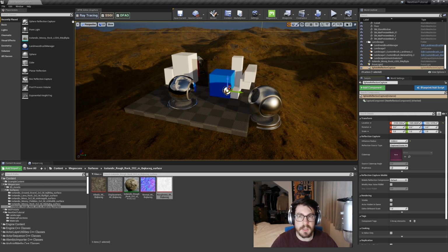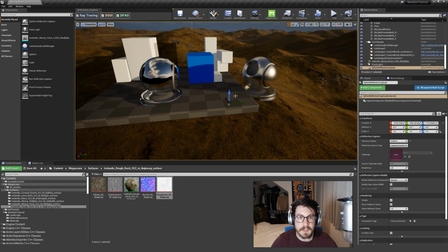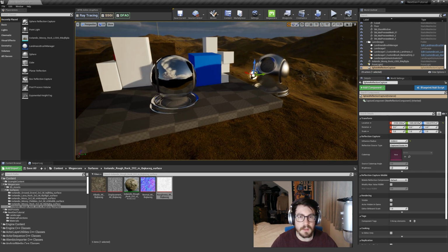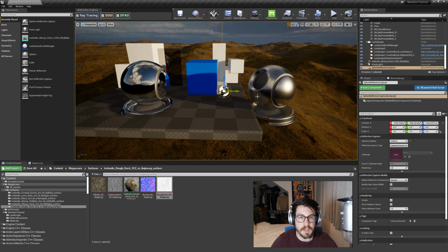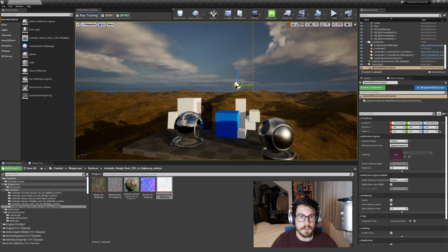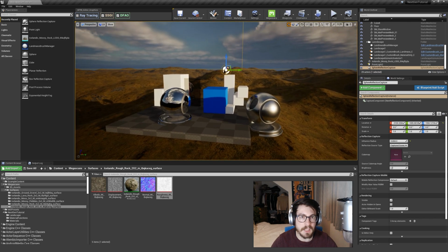This is of course because we're not in the ray traced mode, right? We are in the screen space reflections. And unfortunately in these capture spheres you don't really see the environment, it stays black, but at least it's better than nothing. You can also move these around, and you can see that the reflection moves around with it. But I think it's fine at eye level height.